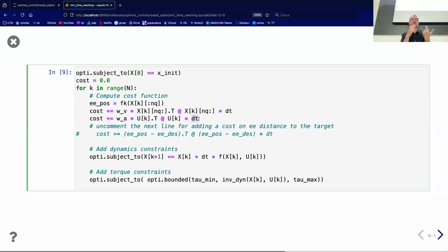So when I switch to discrete time, the integral should contain the dt over which I'm integrating. If the dt is fixed, of course, there's just a multiplication of the cost by a constant value, so it doesn't affect the optimum. But in this case, since this value dt is not constant, it needs to appear in the cost function integral.